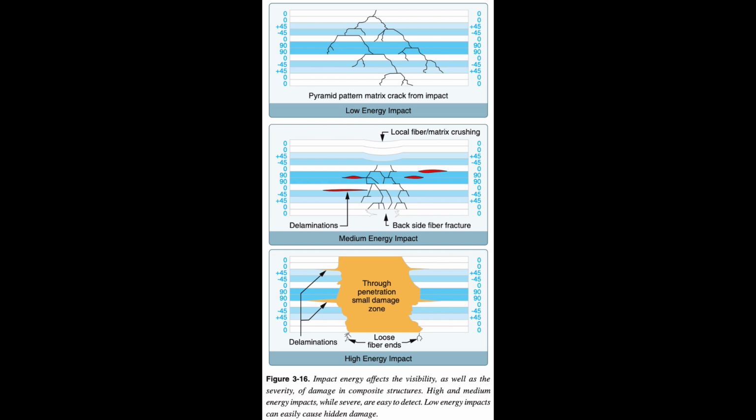problems later. A piece of speed tape over the puncture is a good way to protect it from water, but it is not a structural repair. The use of a paste filler to cover up the damage, while acceptable for cosmetic purposes, is not a structural repair either.